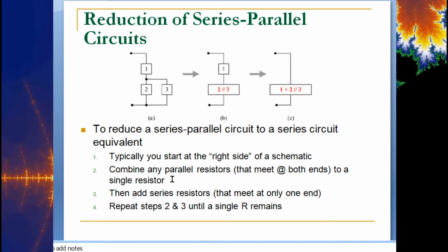So combine any parallel resistors that both meet at the ends to a single resistor, redraw the circuit, and then once you have a series circuit, add them all together. Okay.